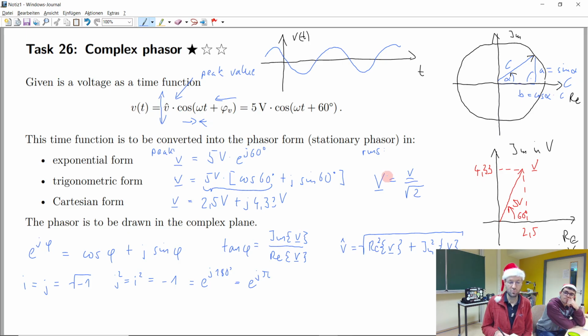And the difference is also important if you calculate power, because if you calculate complex power, maybe I can write this down here. So if we would calculate complex power, it is usually denoted by S. And if you have RMS phasors, you take voltage phasor multiplied with the current phasor, and you need to have the complex conjugate of this. We can discuss also in a second what complex conjugate means. And